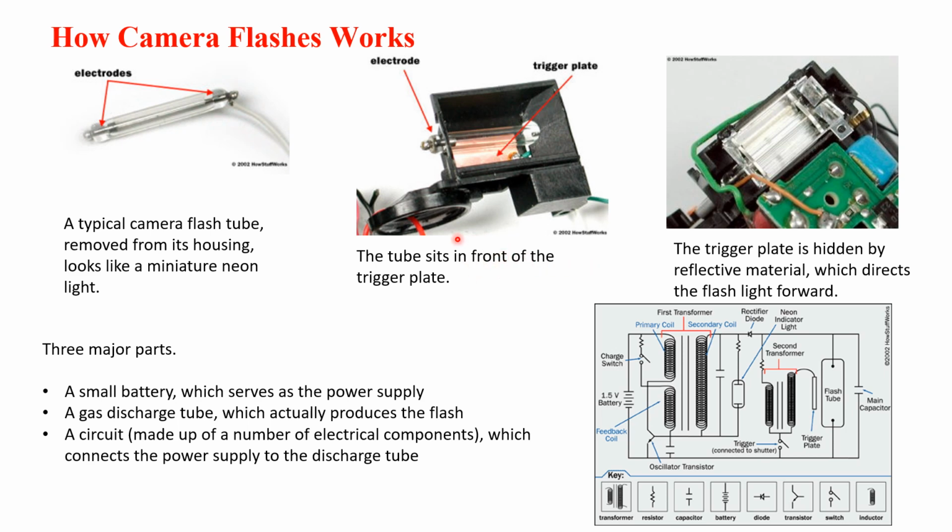That's the purpose of your trigger plate there. Your charges will ionize the gases in your tube, which is composed of xenon gas, and when ionized, the xenon gas creates flashes of light. And when you unclick the clicker of your camera, your circuit will again store charges back into your capacitor.